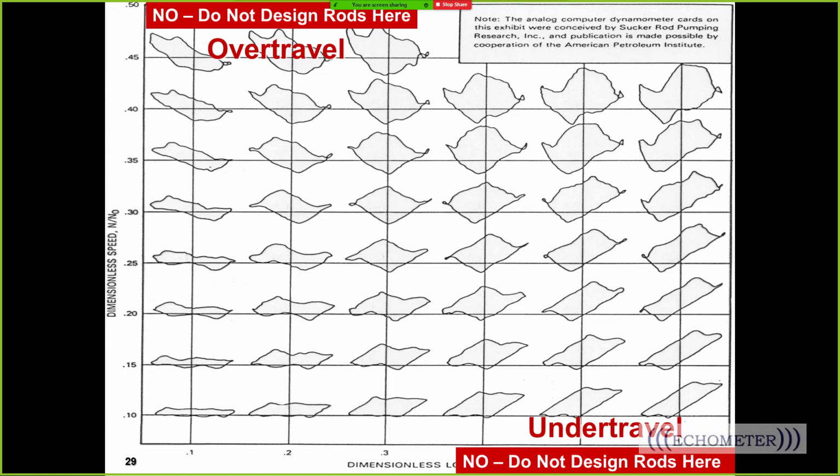Fundamental. I can't remember the name. Parameters, F over SKR parameters and considerations of design of sucker rods, something like that. Norm High and I wrote that because he and I both thought we had the best method to design sucker rods. And what we found was that even though he went short stroke and fast, and I went long stroke and slow, we had the same failure rate, but we had different design methods.